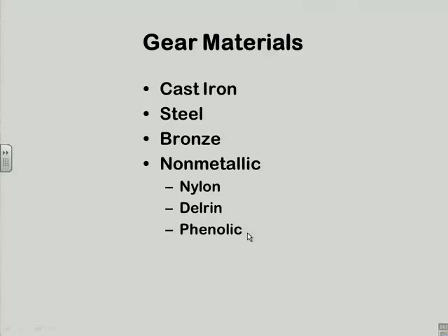The generic name of Delrin is acetal, sometimes pronounced acetal, spelled just like it sounds, A-C-E-T-A-L. There are only 2 companies that make it as far as I know. DuPont makes Delrin, trade name. Celanese makes Celcon, trade name. They are slightly different chemically because of patent issues, but they have very similar properties. They're a very, very good engineering plastic for lots of applications.